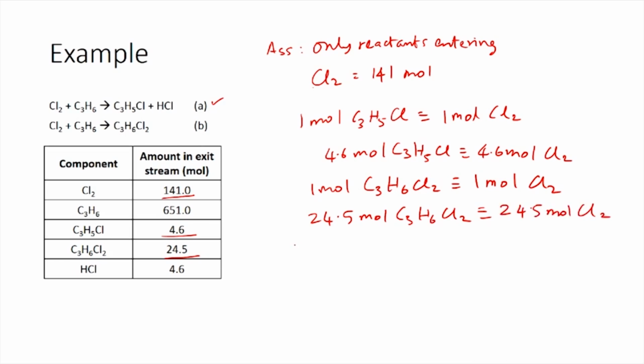So, now that we have calculated these, we can calculate the total amount of chlorine which is fed, which is the input. So, we can go back to the balance equation which we had, which is input minus output plus generation minus consumption equals accumulation. As the process is at steady state, we will have accumulation to be 0, chlorine is not generated. So, you have only consumption. So, you end up with input equals output plus consumption.